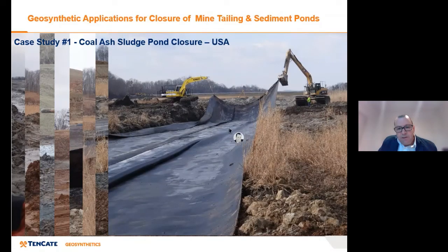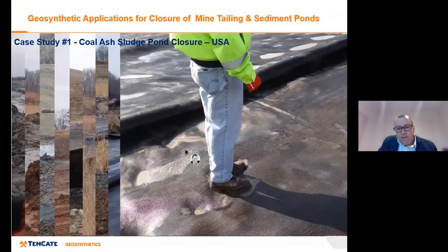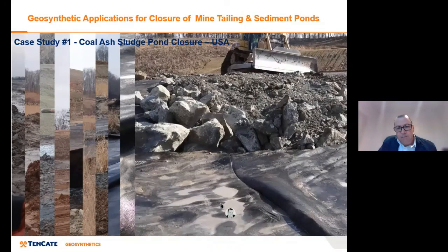Again, you can see the seam, and then you get that separation, you get strength, and you also get the water or the liquid coming through as well. So you get that release of pore water pressure. And the point I made before about the use of cover materials and how woven geotextiles can be quite accepting of a broad range of materials.